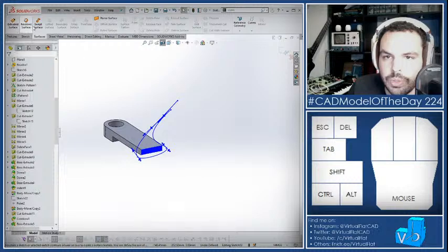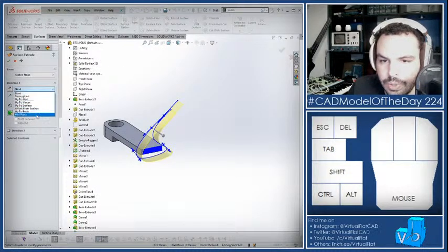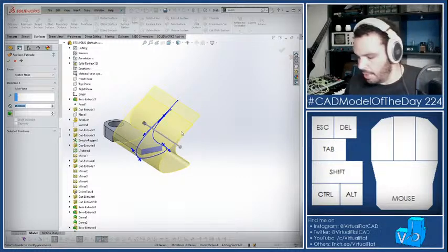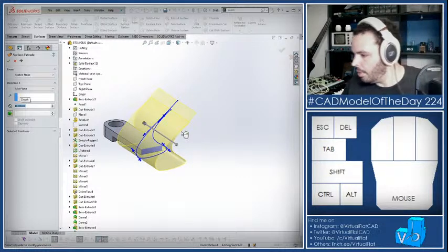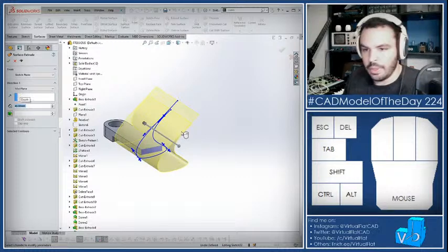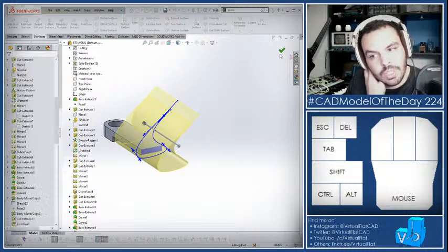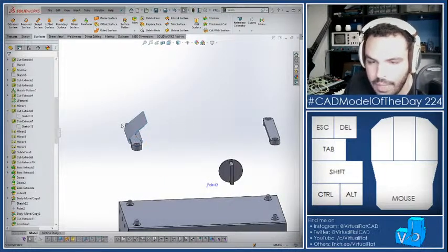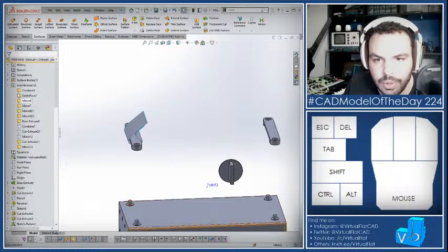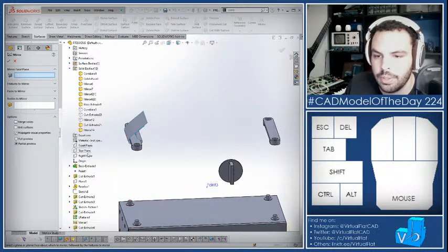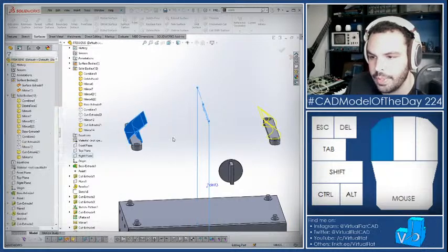And I'll just do a surface extrude. Mid. Maybe like, I guess 40. Verify with a measurement. Like 45. Hit OK. Alright, so I have that thing. I'll mirror that surface body to the other side. Like that.